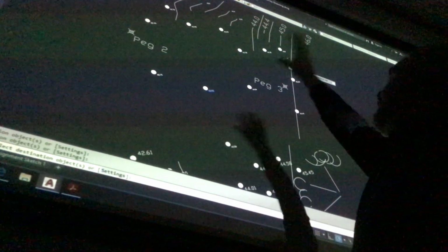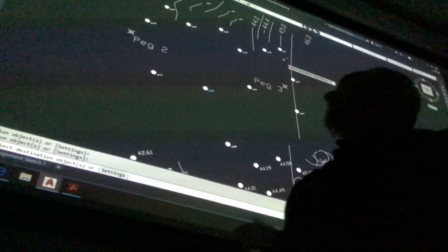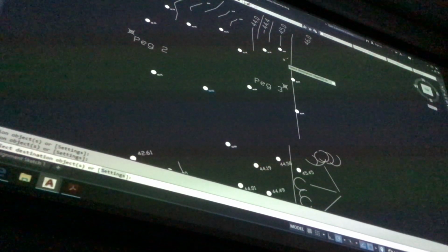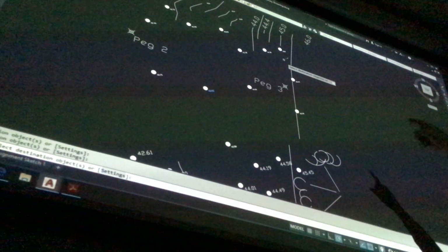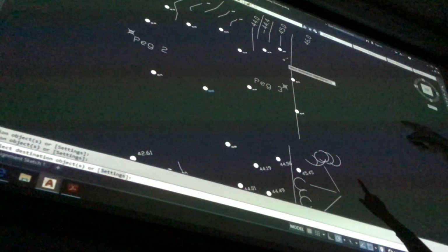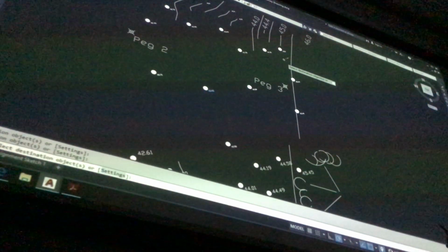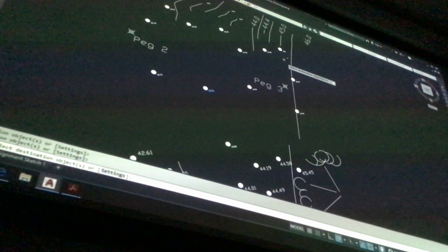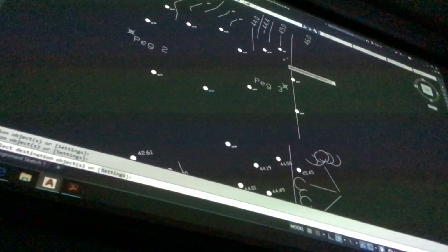Once you've done one, you can whip around and do the other ones. This is a pretty dominant thing on the drawing as well. You're welcome to take the centre point of that and change it to a very small circle, open circle or something. No, not an open circle, that's your traverse, maybe a wee cross or something. Okay? The pegs won't be a cross like that, the pegs will end up a circle. Now those pegs may be in the right place, in which case, yee-haw, I've just plotted two of them for you, and they might not be in the right place. So when you do your pegs, make sure you do them properly, don't assume anything. Never do that with anything, any drawing like this.